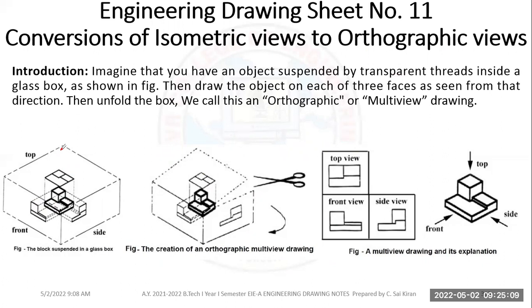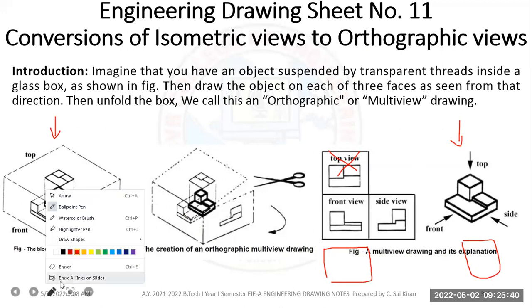Generally in the first angle projection, we will see from the top. This is the top, and it will project here. So what shape are we seeing? It will project here. Because this is a numerical, they have used the third angle projection, but generally the top view you will be getting below it. Because you are seeing from the top, at the bottom you will get the shape. It is a little bit confusing in the third angle projection. So that's the reason in India we use only the first angle projection.